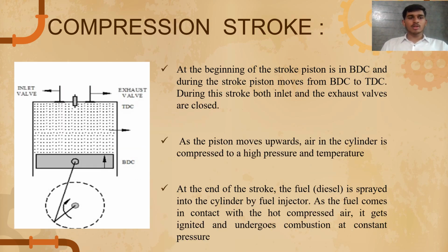So the second one is the compression stroke. At the beginning of the stroke, the piston is at bottom dead center, and during the stroke, the piston will move towards the top dead center. That is, the cylinder is filled with fresh air, and the piston will move from bottom dead center to top dead center. During this stroke, both the inlet and exhaust valves are closed. As the piston moves upward, the air in the cylinder is compressed to high pressure and temperature.